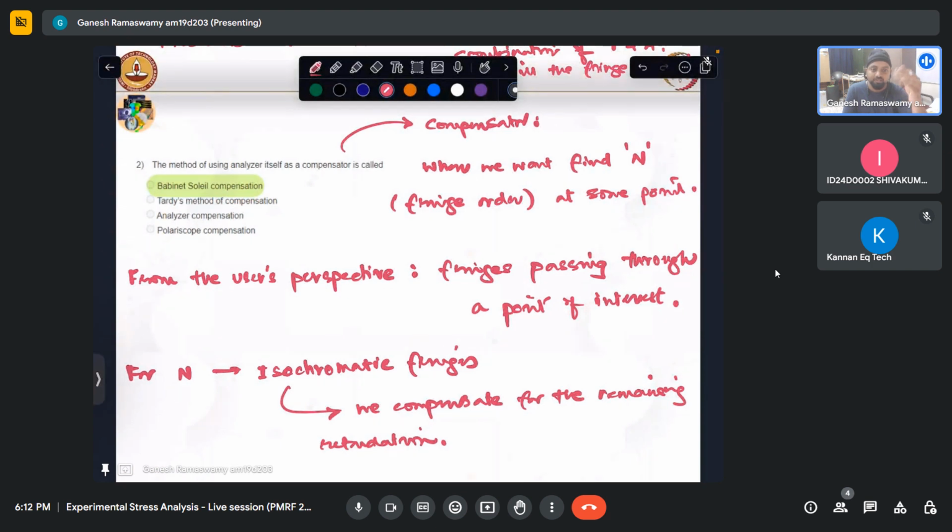So many rotations imply that it will bring about this particular retardation. They have a calibration chart. So we will align it at that point and rotate it till the fringe passes. We'll see what value we have introduced in some other metric, so that we can read out from the calibration chart the actual retardation we have added. So this is an external mechanism.